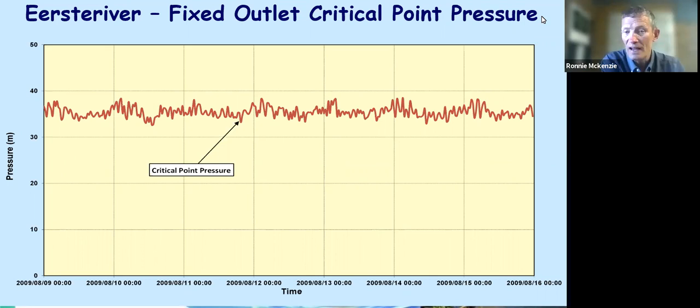We didn't do that initially because to take pressure down at the critical point from 80 meters right down to 20, you'll get a huge number of complaints because people are used to watering the back of their garden from the porch. So you stop them doing that immediately, they'll complain. So you kind of sneak it down over a period of 5 or 6 months. So this is the first phase. We brought it down to about 35 meters.